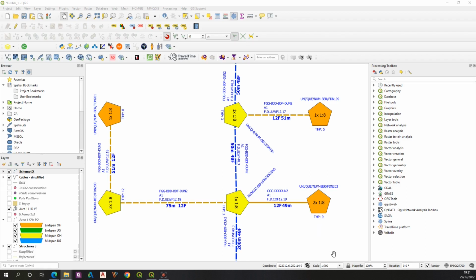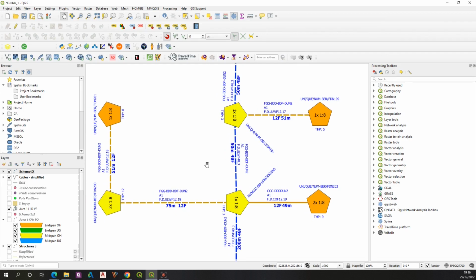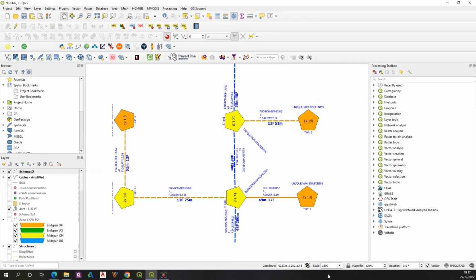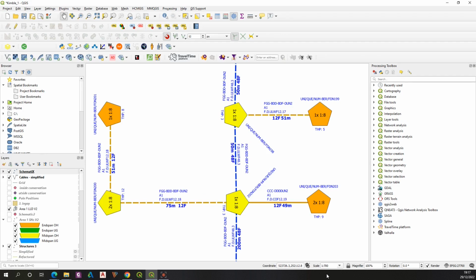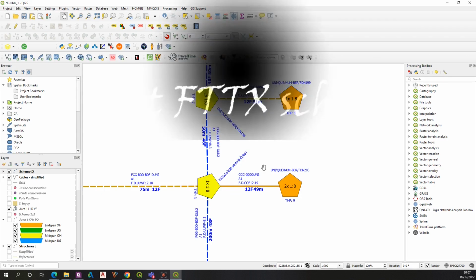That's why a scale such as 1 to 700 is surely optimal for this particular task. It's the most optimal scale for presentation in the PDF version. This is roughly the scale, or pretty much the scale. If you put 650 here, it still should be fine. If you put 1 to 800, it should still be okay. But I came to the conclusion that 700 is the best, admittedly, and this scale has been set as the final scale for the PDF output, which could correspond pretty much to the versions presented at the very beginning of this tutorial. Alright, so let's move to the next step.